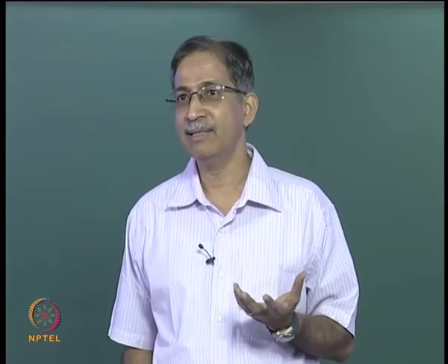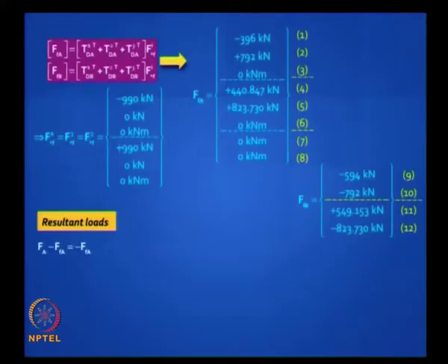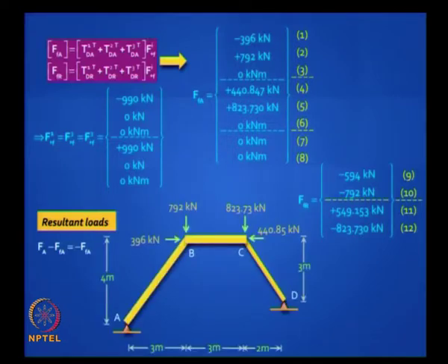And so you can find the resultant loads, which is Fa minus FFA. Fa is a null vector because this structure has no direct loads acting on it, and so this is what you get. It's as though someone is pressing down those corners B and C, and visually it makes sense. That's what's going to happen when it wants to cool, and those loads are not small, they are huge loads, 792, 396. Is it clear? How do we proceed from here?